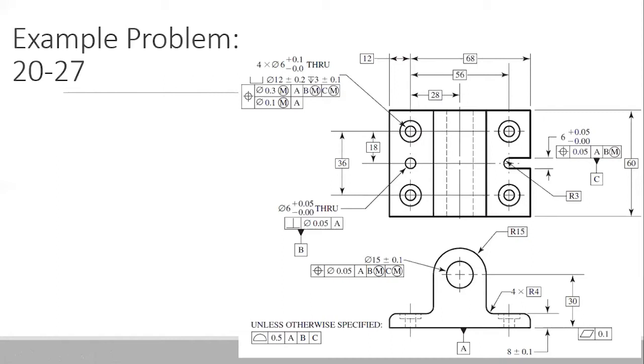What about the one under that, the small one in the middle? Yes, that perpendicular one. Does that just mean the axis has to be perpendicular? Yes, exactly. It basically says that this locating hole has an axis, which is your datum feature, because your reference frame is attached to a dimension.